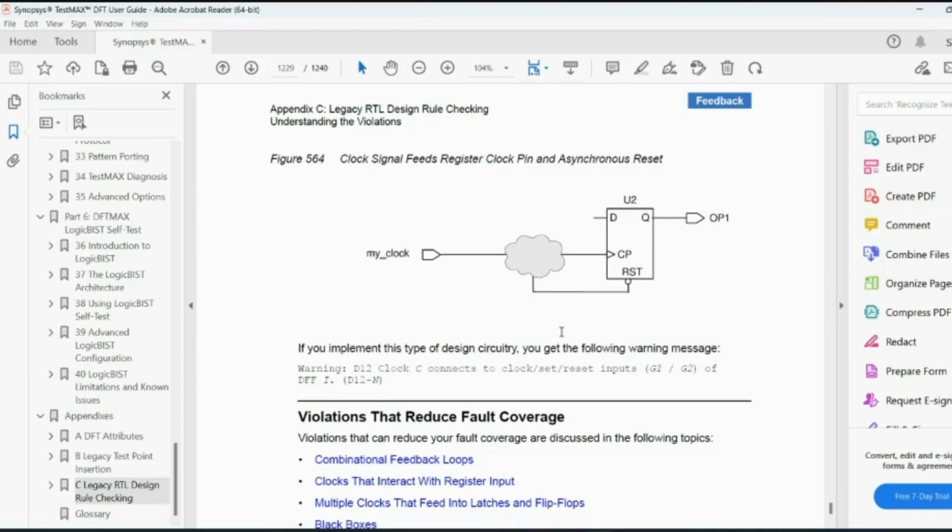And in few teams in real time, the RTL manager says to run Spyglass after RTL design to know the existing DRCs before delivering it to the physical design or DFT team. That is saving a lot of time, actually. Even a few companies do that.